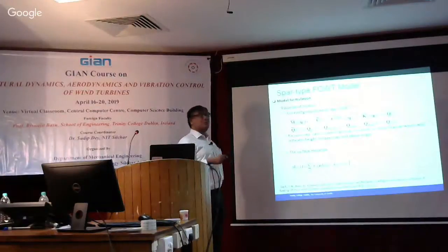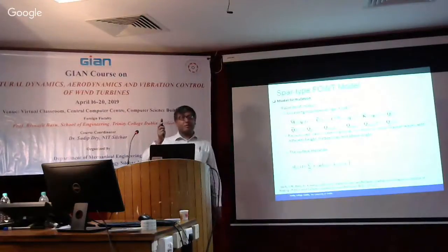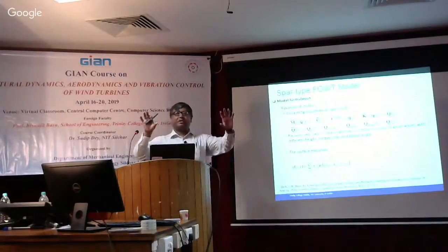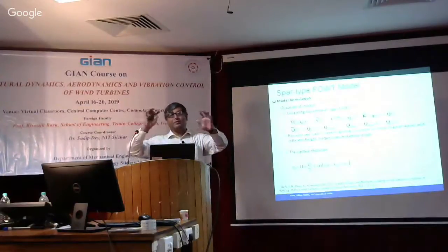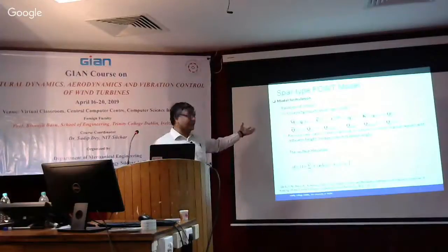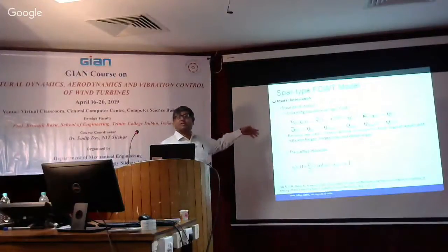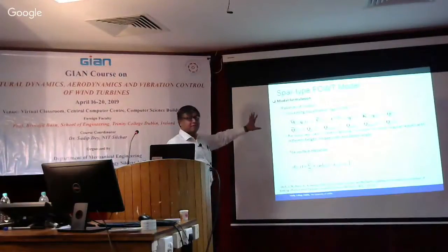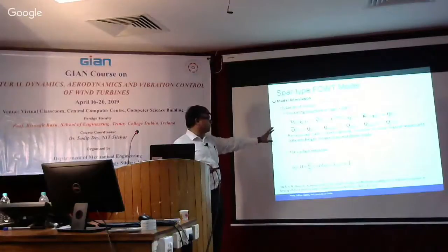And also, as we saw yesterday, we didn't assume any damping, remember? And we got this negative damping terms appearing because of the coupling between the tower and the platform. You'll have similar terms here as well. But on top of that, you'll also have nonlinear hydrodynamic terms leading to these things. But anyway, this is the time varying system we have. And then the surface elevation is presented by this expression over here.